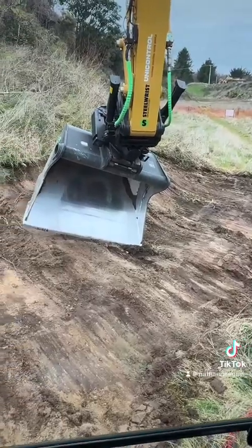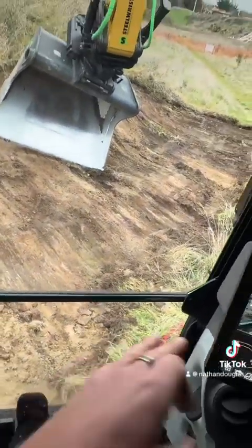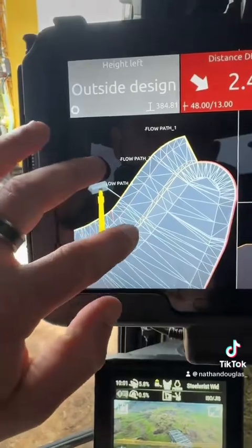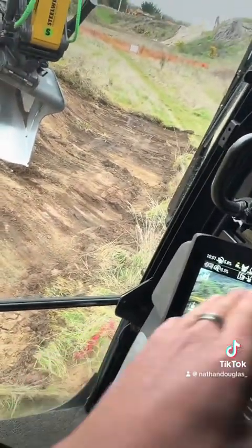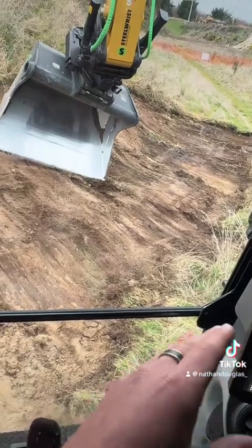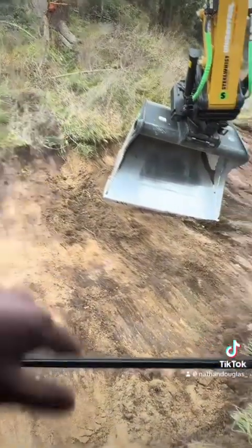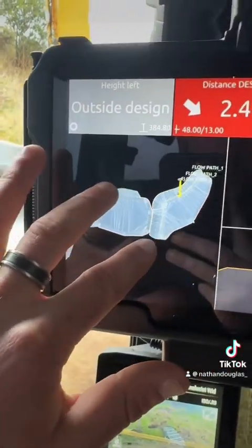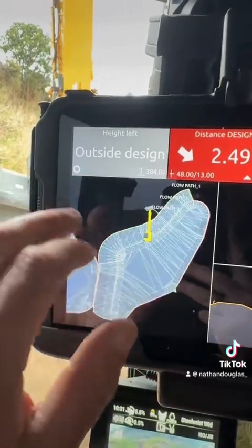What we've done is we've stripped a total of 5 meters from the constructed fill, which is going to be in here. So that line that's 2.5 meters away is the toe of our basin wall. So it'll run down, and then I will create an infield design from the toe of this across up to our 5 meter mark. Because you get designs like this, which is good because you've got the basins and you've got your walls and everything that needs to be in here to build the basin.